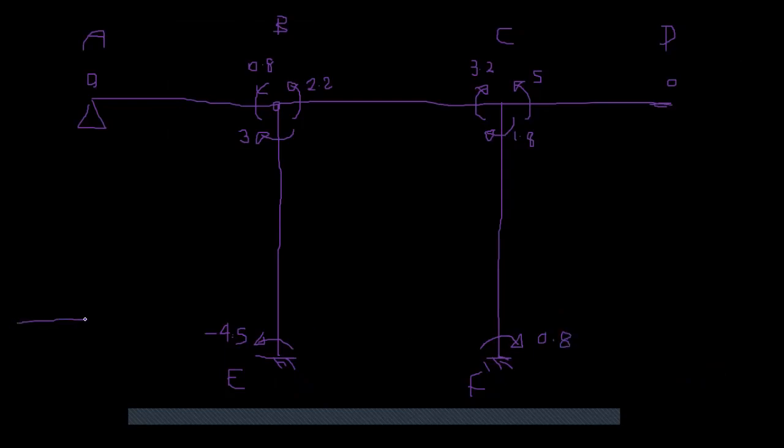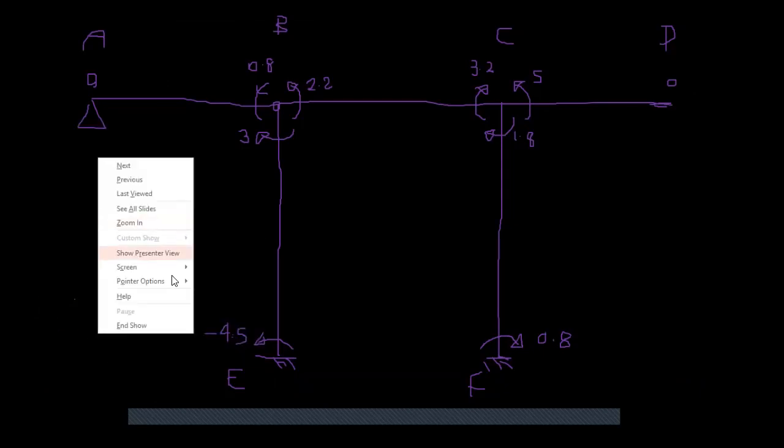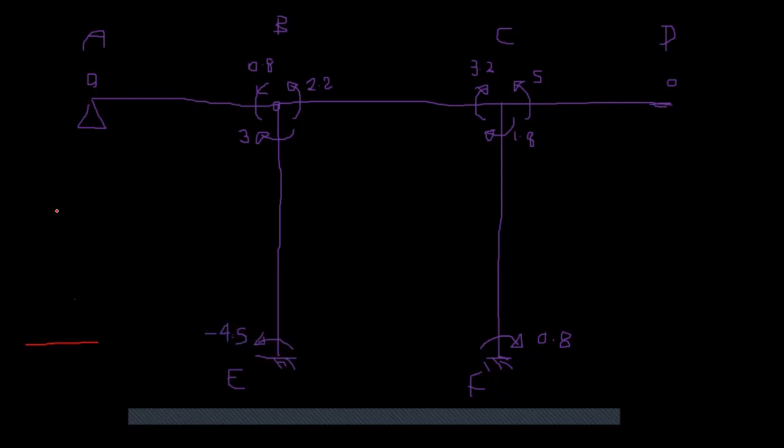Always, some people, if it is anti-clockwise, draw it like this. Not even them, I cannot figure out where the bending moment is, right? So don't do this. If it is anti-clockwise or clockwise, keep it like this. So for this member, keep your finger like this.